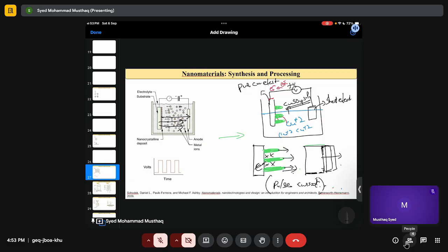Whenever we continuously supply some amount of direct current, there will be this lamellar growth of lead on one plate. Once they reach a certain size, they will short the circuit, which results in explosion of batteries. Which is mitigated right now, but it was one drawback of the liquid type batteries that we use.